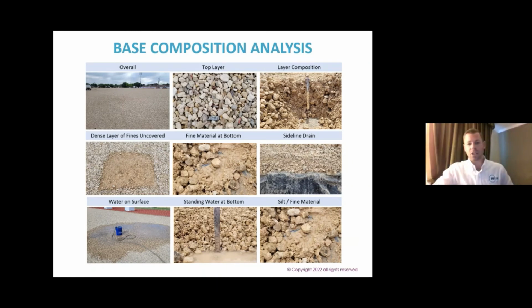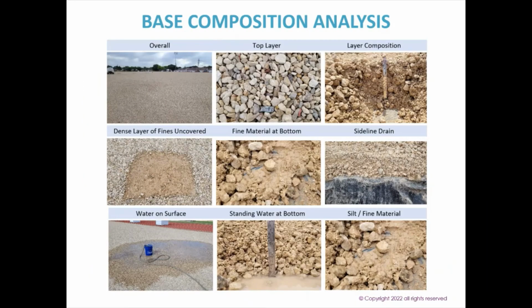There have been a number of cases recently where we have tried to reuse a stone base, and like I said, it looks good on top, but you get down just a little bit, even a quarter inch, and even beyond that, and you start seeing issues. You don't want to lay a brand new field on top of that, because of course that problem is going to persist or potentially get worse depending on the materials you add in.